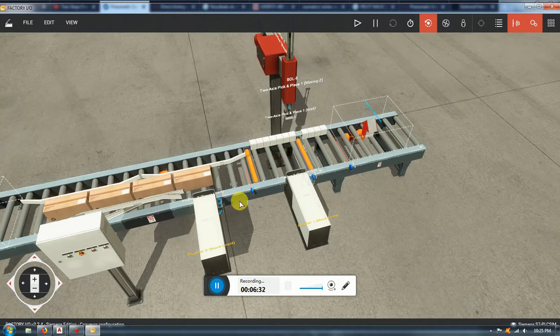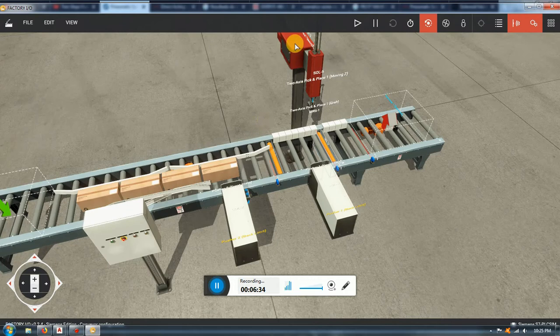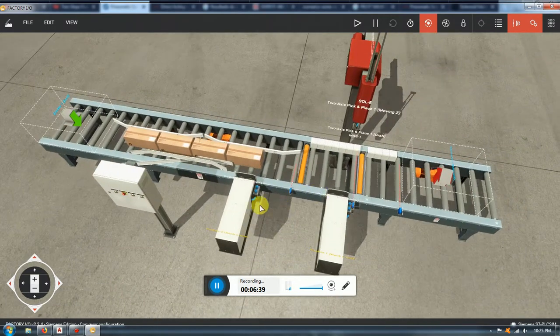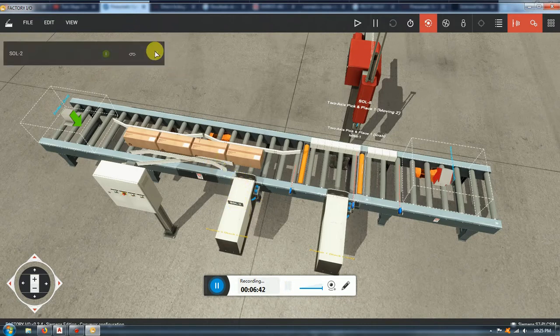In this case, I have 5 cylinders, so I'm going to need only 5 solenoid valves. But you never know, okay? For example, if I'm gonna have a lot of boxes coming, and things have big inertia, this motor is making these boxes go really fast, depending on the speed, I may need more than one clamp to support that one. So no more than one box is gonna be here being pushed, and it could happen.